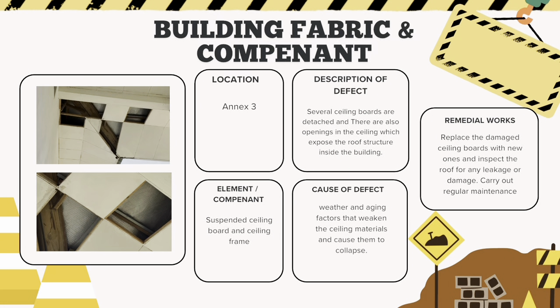This issue is likely caused by weather and ageing factors that weaken the ceiling materials and cause them to collapse. The proposed remedial works are to replace the damaged ceiling boards with new ones and inspect the roof for any leakage or damage. Carry out regular maintenance.